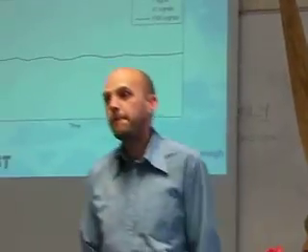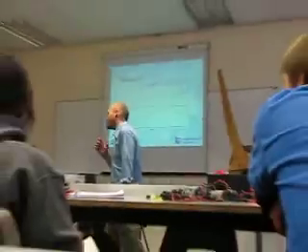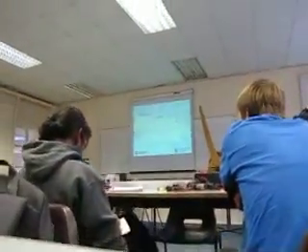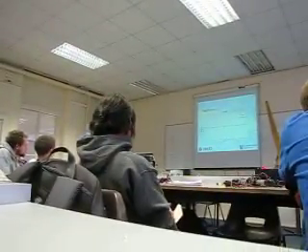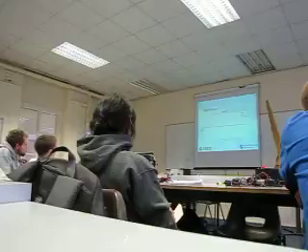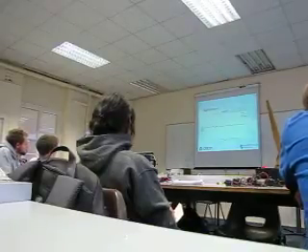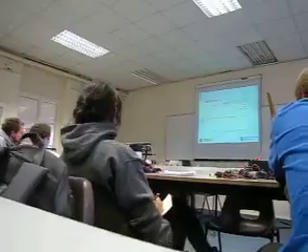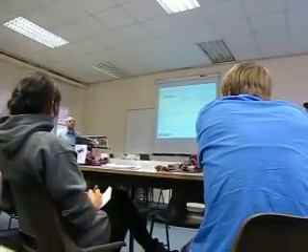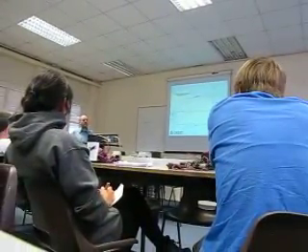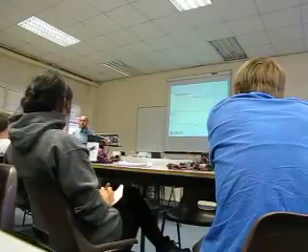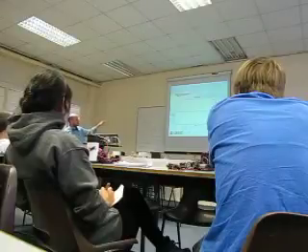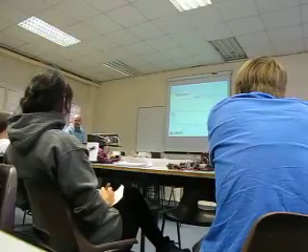Is that like even when all the wind turbines are in the same place? True, there is local dependency on the wind conditions, yes, you're right. Still, the second-to-second variation will be smoothed out by having 10 wind turbines in a place. We do need to distribute it around the UK. Also, there are times when the whole UK has not much wind, because we're in a low-pressure area. At the moment there's not much wind, so the aggregated output is very low.